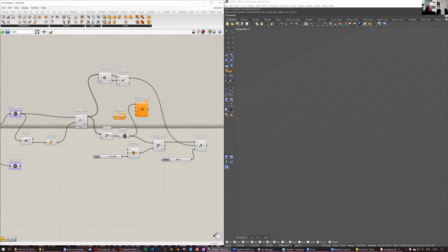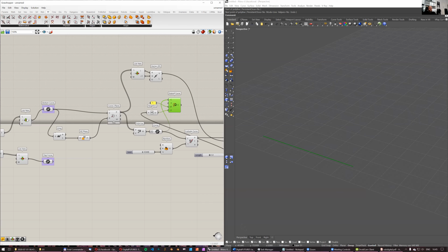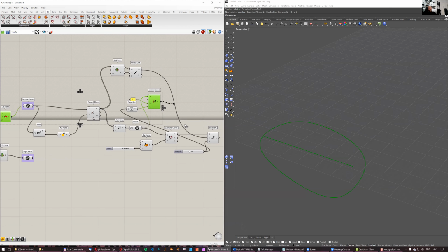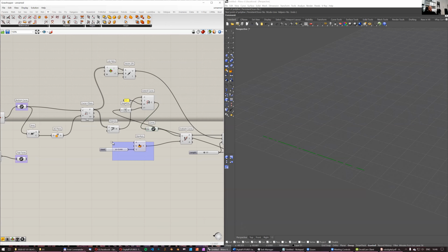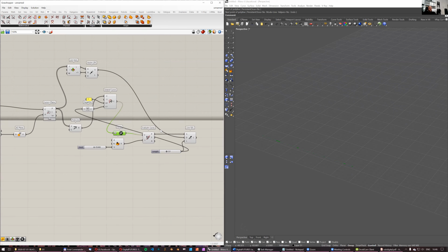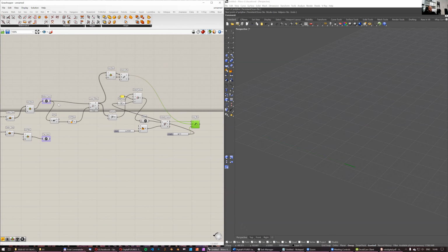So if this is the length, I will set the negative number here and 0 here, and I hope it makes the curve shorter than it was. And it seems like it works. Yes, now this is 3 units shorter, so I will plug it here and here because I'm reparametrizing here. So I'm absolutely sure that the bottom edge of the leg certainly remains inside of that curve, this one.